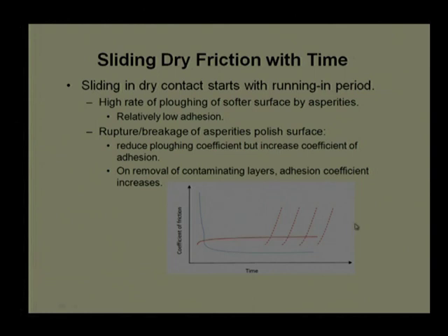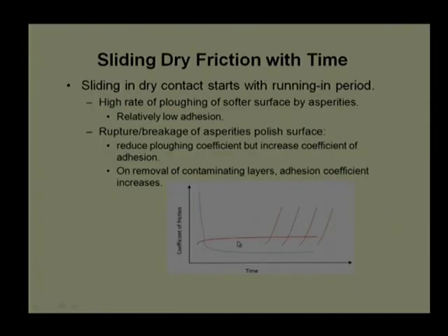So, that is why we are keeping these as imaginary lines. They depend on the load condition, on the temperature, and on whether the lubricant layer was initially there and was removed from the surface because of starvation, pump failure, misalignment, or some other reasons. So, there is a possibility of this kind of hypothetical lines.